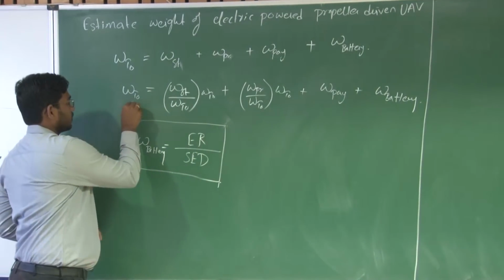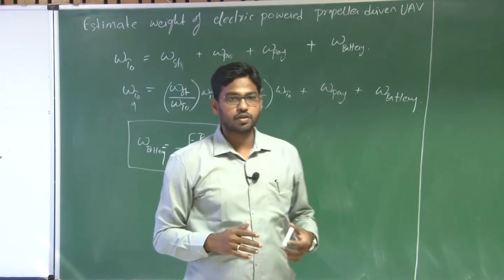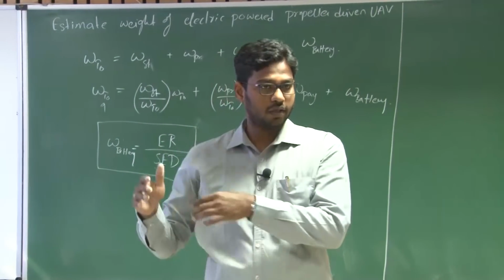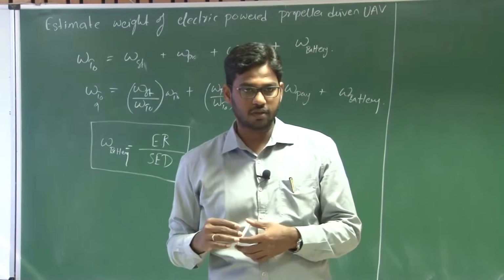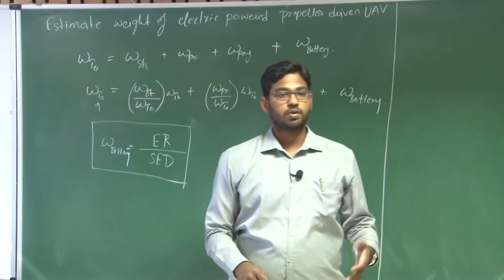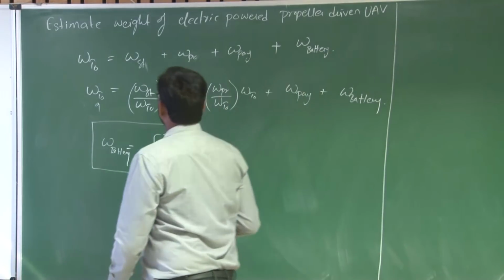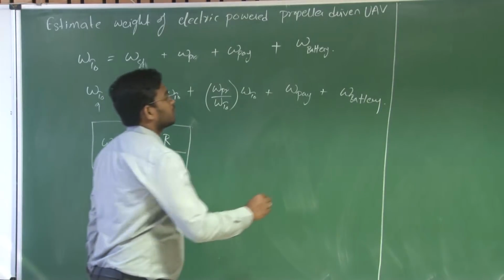Takeoff weight is known, but say if you are starting a new design of a new UAV where you have only a set of mission requirements, but you don't know what is the overall takeoff weight, how to start or how to solve that problem, right? So the approach that we are going to adopt here is an iterative approach, right?